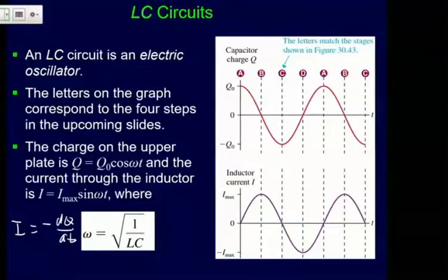And then what happens is when the charge on the capacitor is 0, when the capacitor has discharged all of its charge, which in an RC circuit would be done at that point, in a capacitor and resistor. What's happening is at that point you've got this current in the inductor, and that current can't just stop immediately. So that current keeps on going in such a way that it charges the capacitor the other way. The capacitor started with positive charges on the top, and then it'll end up with negative charges on the top as it charges itself the other way. And then basically this thing just repeats.